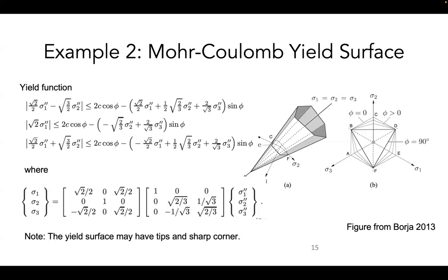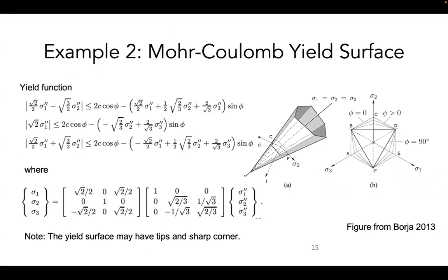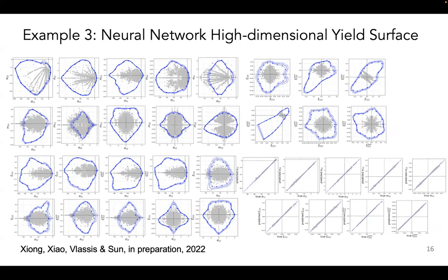Before you solve the problem, the smartest way to do something is to figure out the easiest way to do it, or as my student likes to say, the least implementation of something. Sometimes that's the best solution. I also want to point out that there are other yield surfaces. For example, you can create a micromorphic yield surface, but that becomes really hard to write manually. You can see that there are 27 of these boundaries. I'm not smart enough to come up with an equation that bounds all the points on the yield surface. If you're smart enough, let me know. I would like to hear what the equation is, but you need to capture all those shapes.